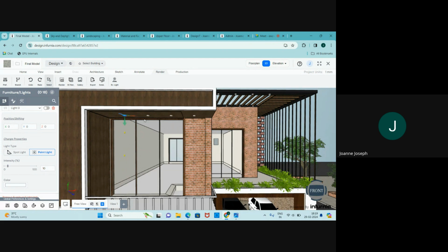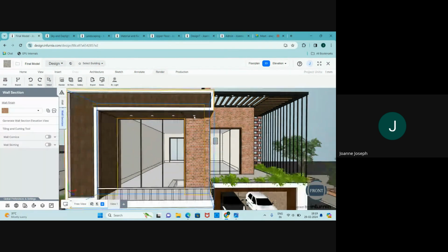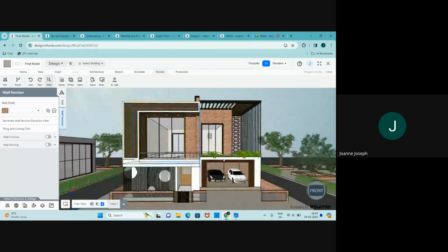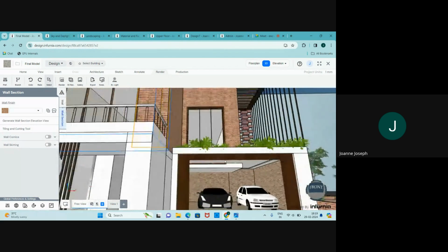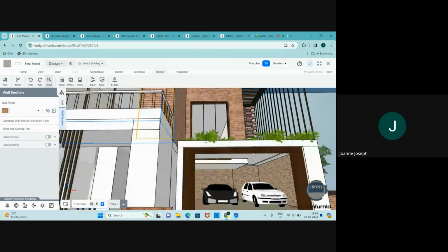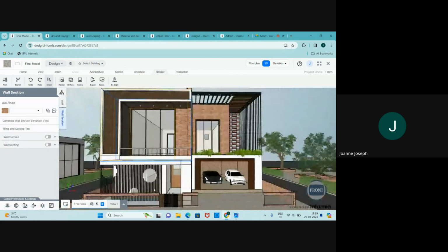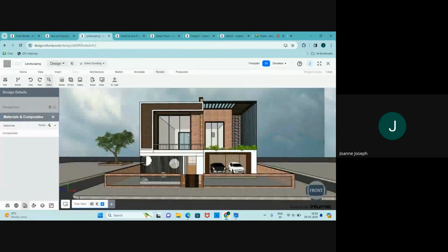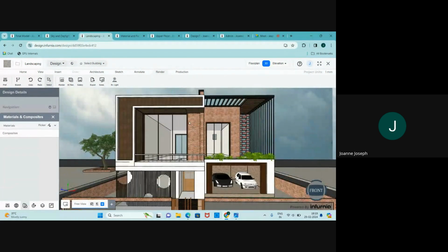If you change the intensity to 10, this will make sure that there is absolutely no glare. So I've placed this at various parts to make sure that the niches inside this design are not too darkened. So similarly, in this case, I can add lights here as well.